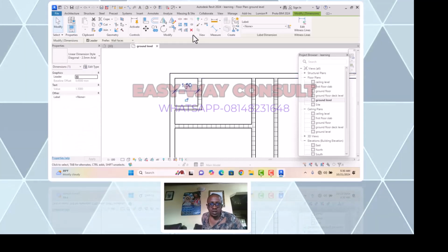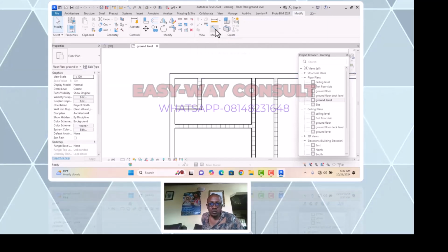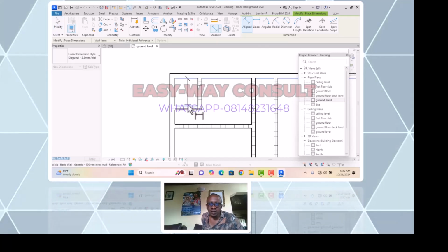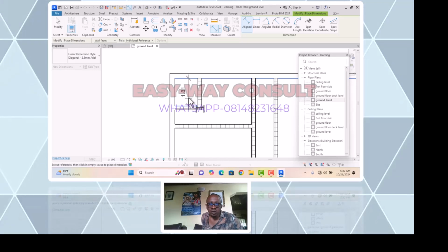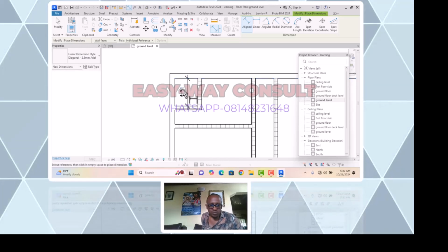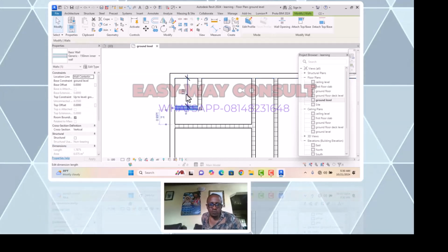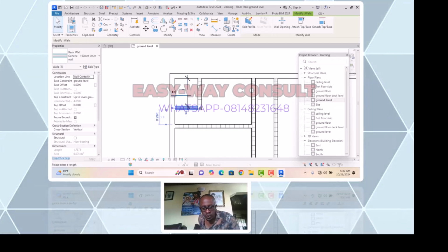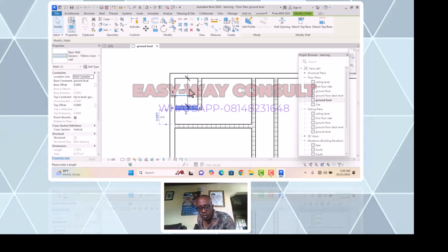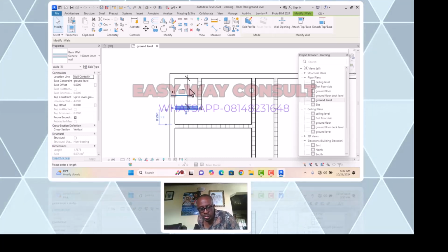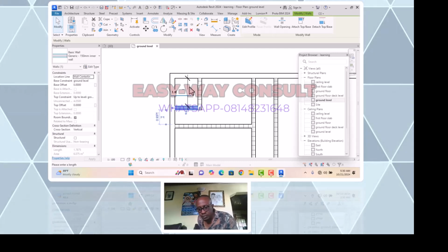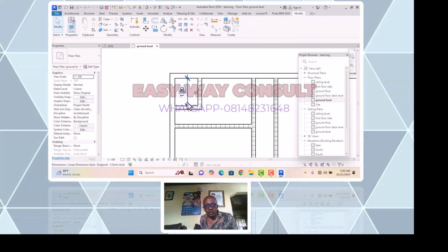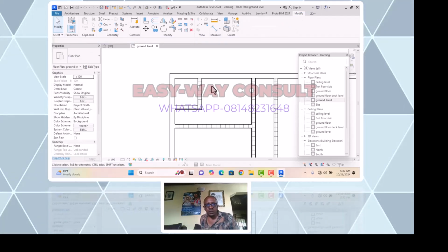You delete this dimension. Now dimension this to make sure you got exactly what you want. So I go back here, I click this. Let me say it's 180, I mean 1.8. You click on it to give you exactly 1.8 here. You delete this.